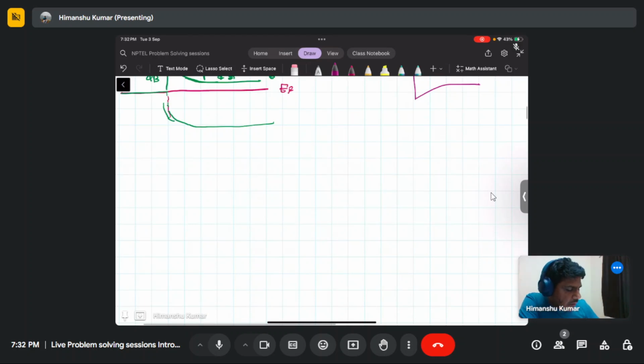You can make a gate, and the gate is basically a dielectric, and then the source and drain, where you make an ohmic contact in the source and drain region. So this is n plus, this is n plus, and this is p. Basically, you make an ohmic contact in the source and drain region so that you can have effective conduction in both directions, from source to drain and drain to source, forming an ohmic junction.